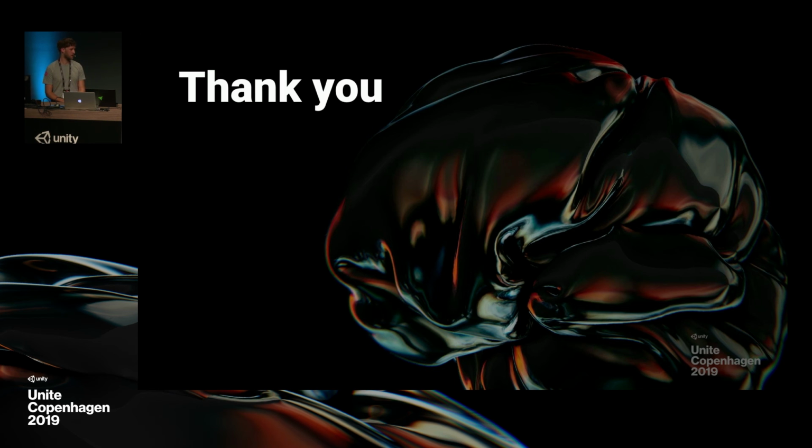You're welcome. We have 2 minutes left. One more quick question. For example, typically on the car, the 4 tires are the same. Do you have an algorithm to detect that so that the mesh is the same for the 4 tires? Yes. Most of the time with CAD files, there are instances, like I said. So basically, you would have only one subassembly for one wheel, and it will be repeated 4 times. So when you do the job once, it will be automatically done for all the others because they share the same reference. And so the pivot would also be properly oriented. Sorry? The pivot of the tire would also be mirrored.